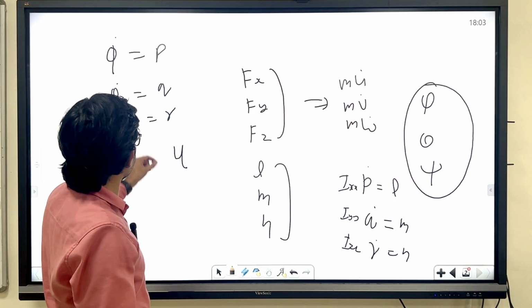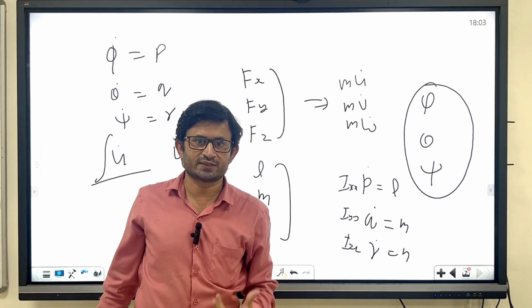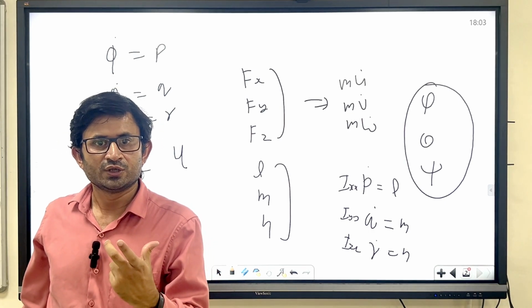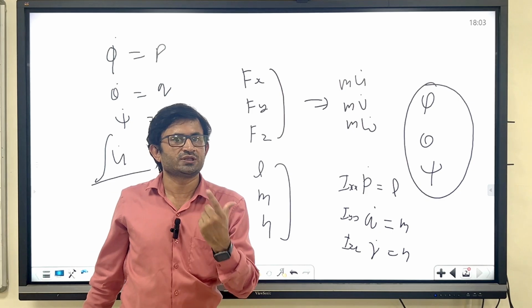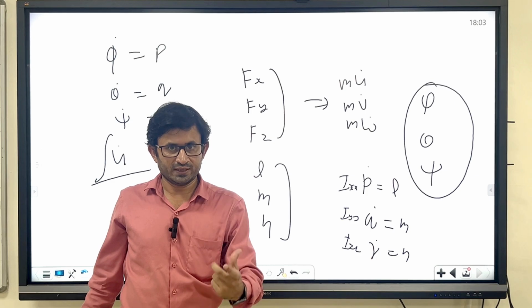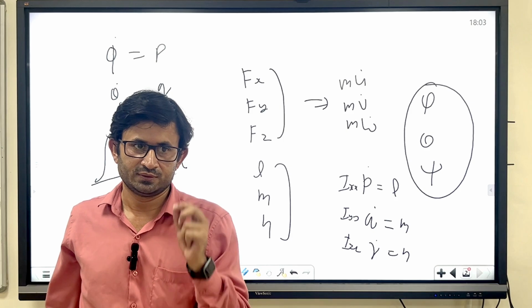So now you will have u, v, w, p, q, r, phi, theta, psi, and x, y, z. So there are 12 states. These are called aircraft states. With time you have to see how my aircraft is behaving, where it is going. From these 12 states, actually, you can check.